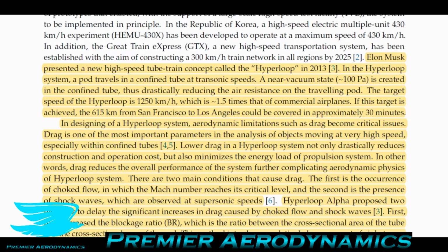But they finally found that the best way to do that is by a clever design, and the way to do that is you make the front of your object sharp, and you make it quite slender, and you don't make any sudden changes in the cross-sectional area. All these things that you do will make it easier to meet the speed of sound and break the sound barrier. And so finally they broke it in the 50s or so.